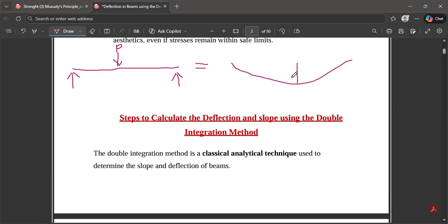So this displacement of the beam at the end of the day is known as the deflection, and that is what actually causes so many buildings to collapse. After this deflection takes place, the next possible thing that can take place is shear force. This dashed line I'm putting here was the initial position of the beam. Now you see how the sagging has occurred, and the deflection is denoted as y. In some books it may also be denoted with different symbols.